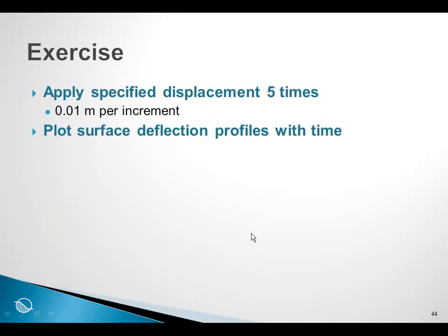This brings us to the end of this session on a load deformation type of analysis, where we have done an incremental stress analysis. We have applied a stress boundary condition, a displacement boundary condition, but most importantly of all, this session has introduced you to the concept of an incremental analysis. And it has to be very clear in your mind when you are using Sigma/W that each load step produces an increment and the increments get added up together.